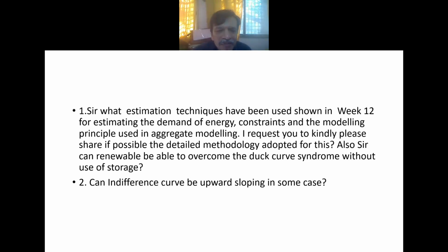That means you can have biomass which can be stored along with the solar, and that biomass can be ramped up. Typically, demand response could also be used. But usually, this can only be planned with either more flexibility in the way we run our thermal plants, or by using biomass, or by using storage. And hydro, of course, can provide a solution.